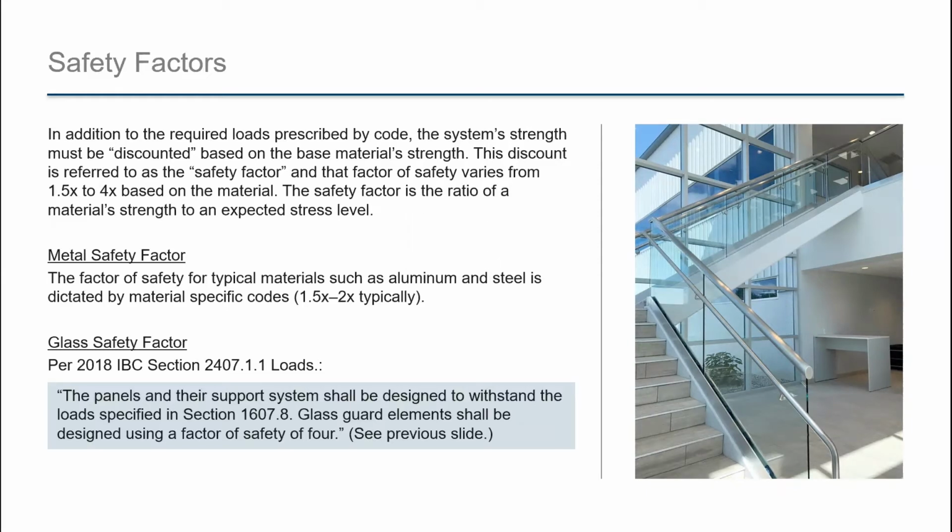Again, when glass breaks, we don't want to leave a big hole there for somebody to just fall straight out of on a balcony, for example. So it's important that it has some post-breakage structural integrity. It's also important to distinguish between testing and engineered design. They occasionally get confused with one another. Factors of safety are relevant only to engineered design, not testing.